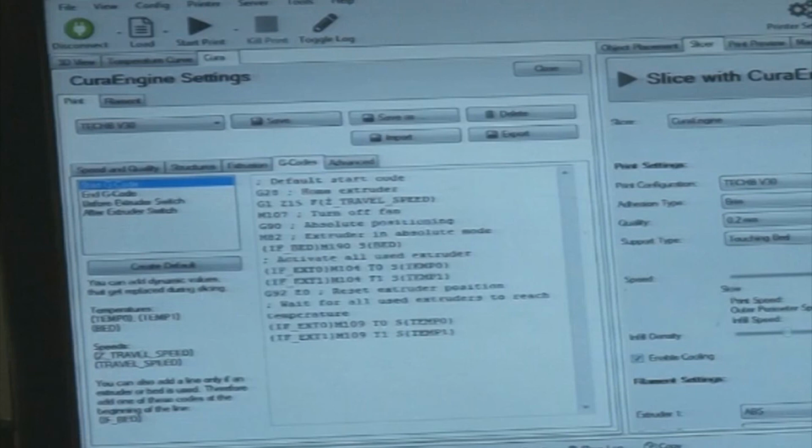This programming system is known as the G code programming system. If you know CNC programming, you might be conversant with G codes and M codes. These are mostly used for CNC programming like milling, turning and other machining. The same code is used here in 3D printing for the movement of the head over the bed for depositing the material.